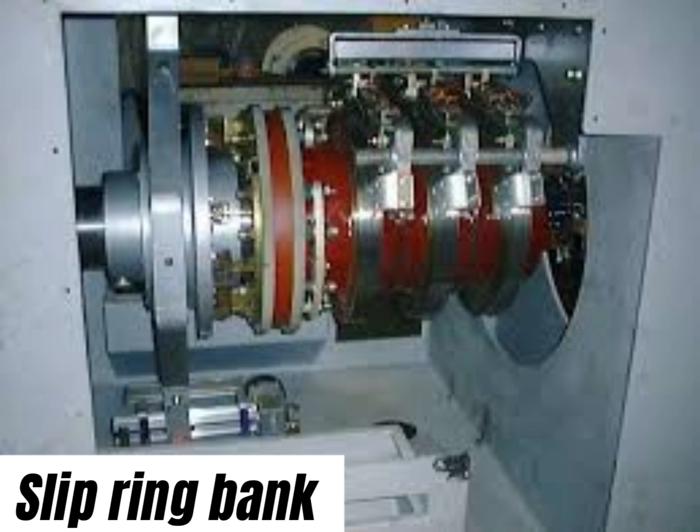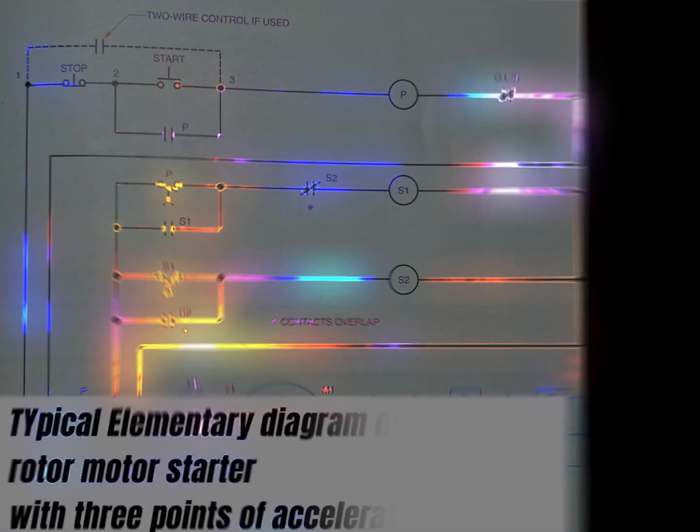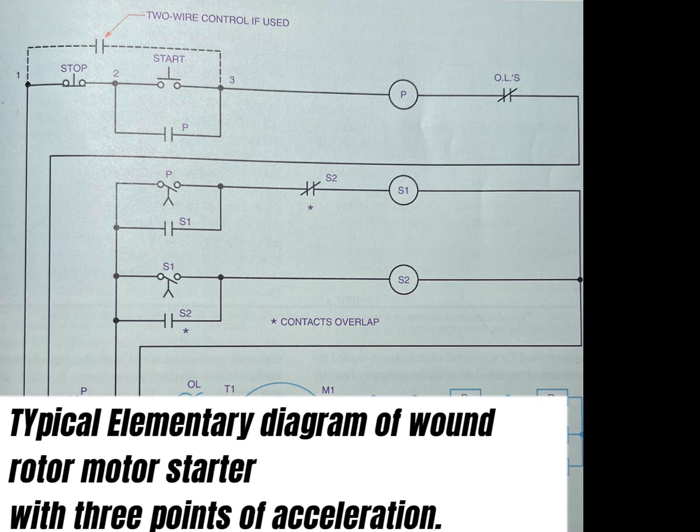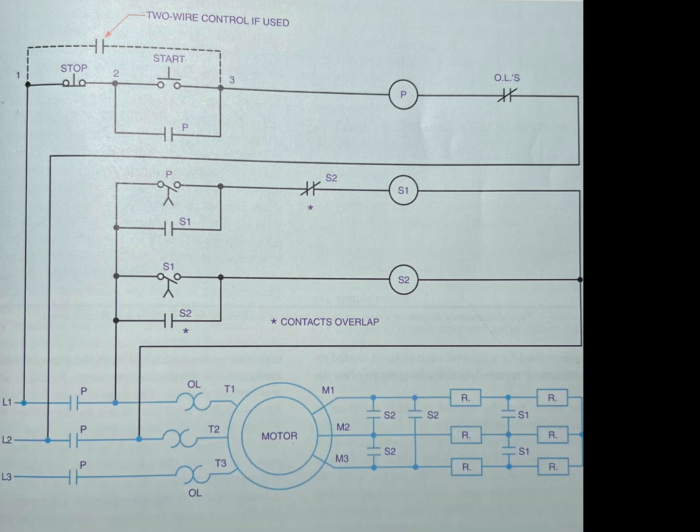Resistors for acceleration generally are designed to withstand one 10-second acceleration period in each 80 seconds of elapsed time for a duration of 1 hour without damage.